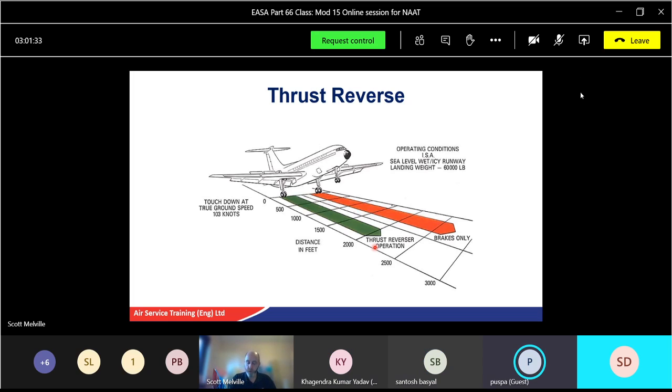All right. Power turbines, free turbines. Again, we're using what type of aircraft? A helicopter or propeller aircraft. Yeah, good. Okay, and the one that's in my book, not in the PowerPoint, was how can we increase the power depending on materials or provide more torque? There were 3 things: temperature increase, diameter enlarge, and RPM increase. Yeah, good. Temperature, diameter, and RPM.